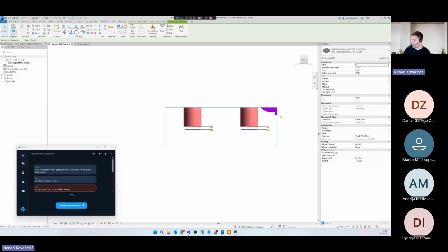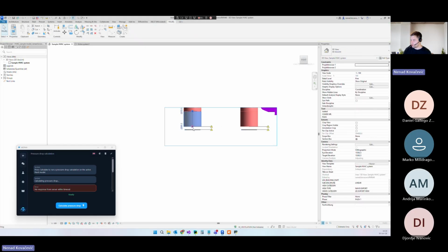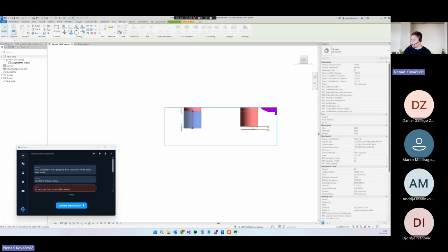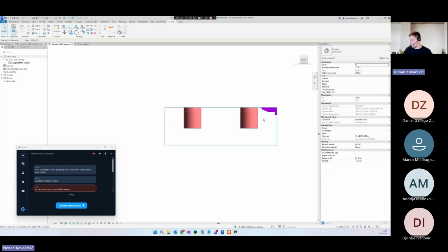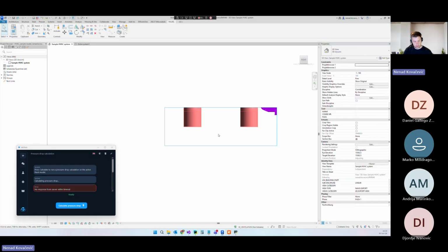So when I took now the return family, the airflow is 0, so I need to move it to the 600 cubic meters per hour. I need to connect them. And because I did push it 50 millimeters down, I will now return it to 2.8.